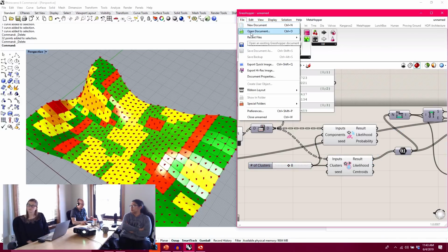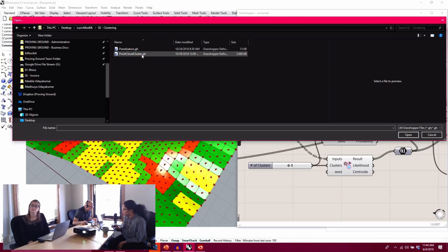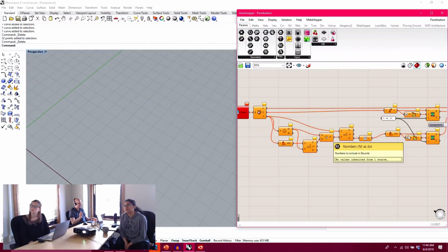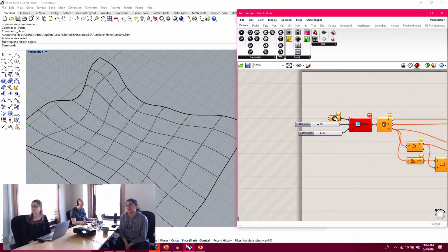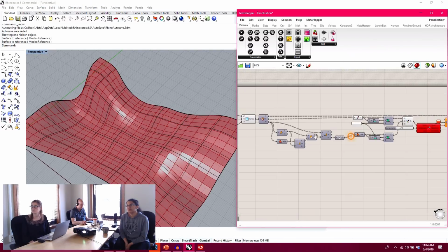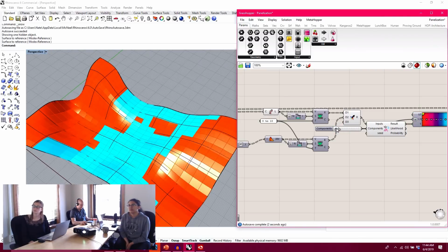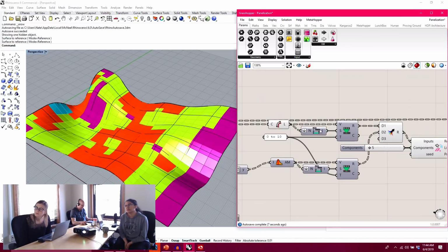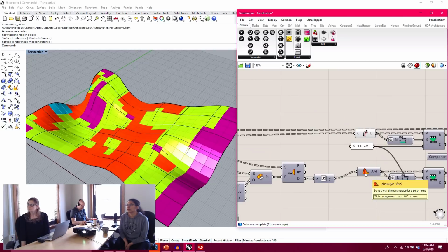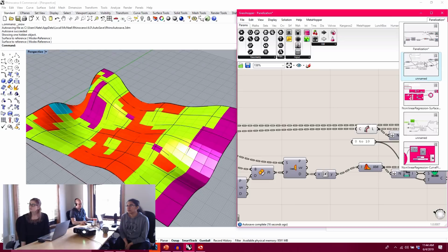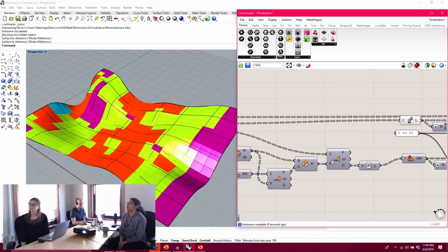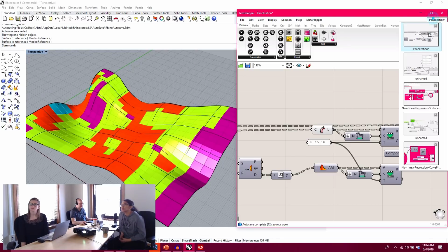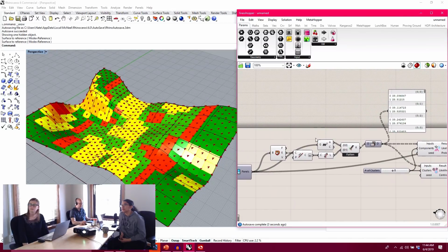So I think the example that I have in our example documents has here's the panelization 1. I think it's almost identical. Yeah, it's kind of the same type of thing. And let's see what attributes I'm actually using. Yeah, I think in this example, instead of using the attributes of length or area and perimeter, I'm using planarity, doing a planarity test as well as the perimeter length test. But I could also go over here and easily extend this scenario to include those other attributes.